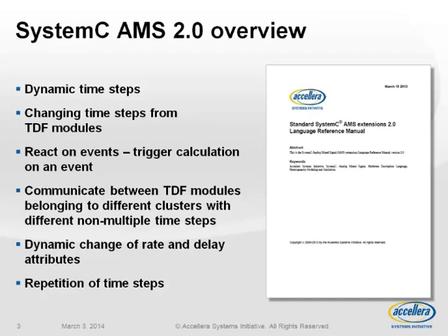The new features which have been added in the SystemC AMS 2.0 standard are dynamic time steps, the changing of the time steps in TDF modules during the course of simulation, the ability to react to events and trigger calculations of TDF clusters, to enable the communication between TDF clusters running at different time steps by special declustering ports, and also the ability to change the rate and delay attributes of the TDF cluster.